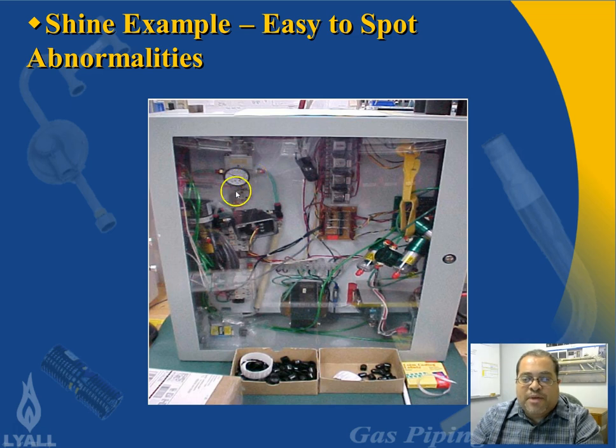But a better way of doing it is look at the piece of equipment from the point of view that you want to be able to detect any abnormality. And in some cases, what that means is extra transparency. So you actually would cut out and make visible all the parts of the equipment, so that you could see small defects occurring before they become a bigger problem that's obscured from everyone's view.